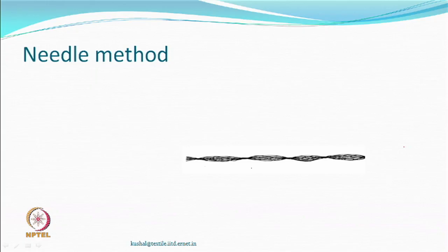So, you did have ways in which you could do that. So, needle means that there is a needle which may be here. When it is impinging, the needle going like this, there is an open area goes down, a closed area comes up. So, this motion would be monitored by this LVDT type of a transducer, and then you can count how much down, how much up it's happening.